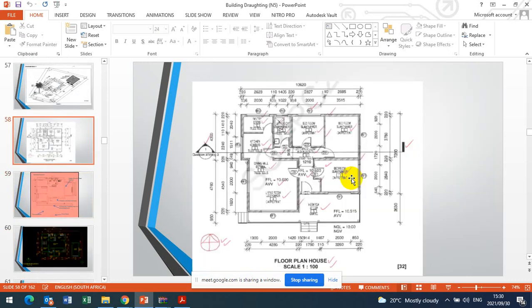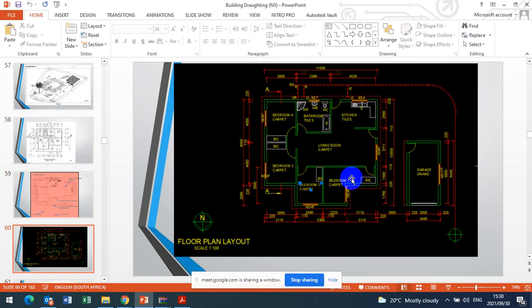This one anyway, it's an example of a finished floor plan from an examiner. Detailed, we'll come to that. I'm looking for a site plan. All right, in AutoCAD, the drawing must look like this. Can you see the drainage pipes coming to the main municipal line? This is the drawing. Look at the layers, standard layers. These fixtures, the toilet fixtures and the rest, you can leave them on the same layer you find them on, because the gray layer is not very dark when you print.